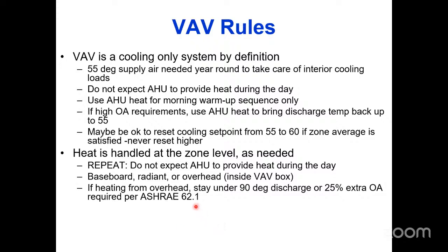There is a long-standing rule in ASHRAE 62, which is the Indoor Air Quality Standard, and the International Mechanical Code, that you need to have low discharge temperature for overhead heating. This has been there for a long time. I know most people don't follow it or understand it, or maybe they don't care. You can't have really hot air coming out of the diffuser, right? So that diffuser, well, that's a pretty bad, I should have showed you that view.